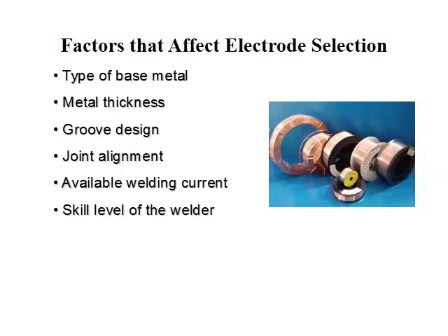Factors that affect electrode selection. Type of base metal. You absolutely have to know what the base metal is before you start welding on it. Nothing will create bigger problems down the road than not having a positive identification of the base metal. This also can drive welders and welding engineer type people absolutely insane.